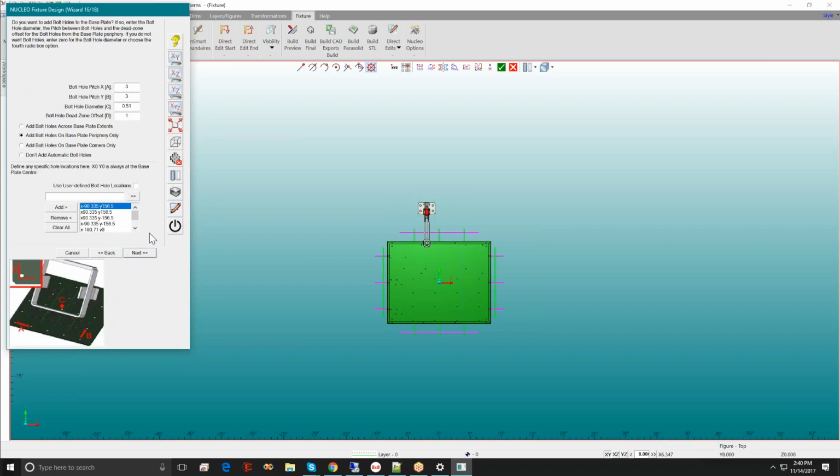Bolt holes. This is where the bolt holes go in the base plate. So you've got your OTC, you've got capital cell. There'd be 3-inch intervals. Just make them the 1/2-inch holes. You can tell it to do it across the whole base plate or the corners on the edges, or don't bother. Or you can also create them, use it to define positions. You just pick them or type them in, and then it will put them there every time if you check the checkbox to say so.